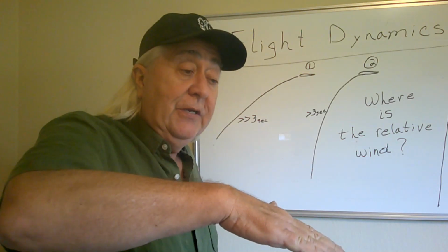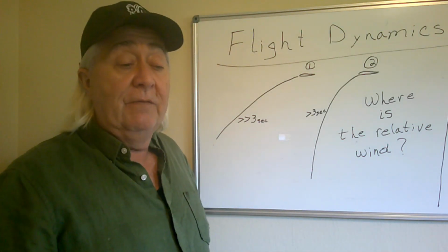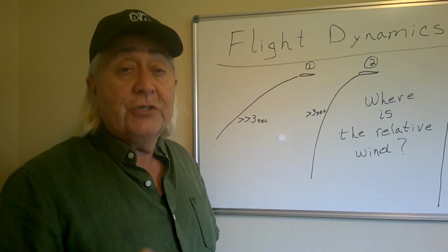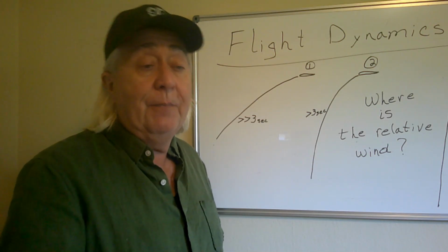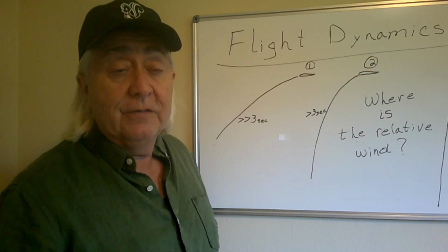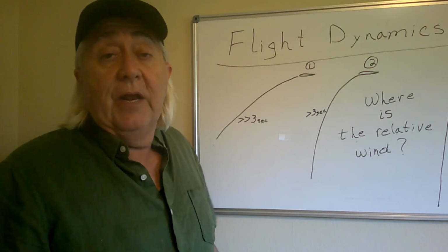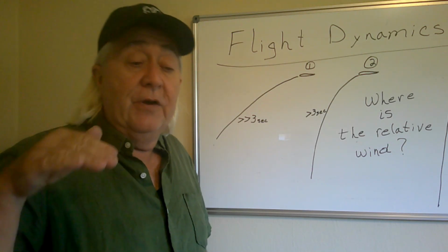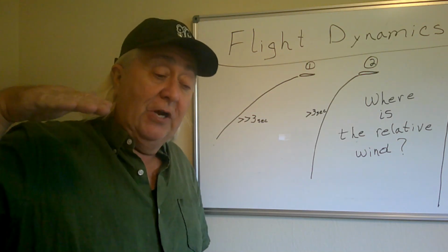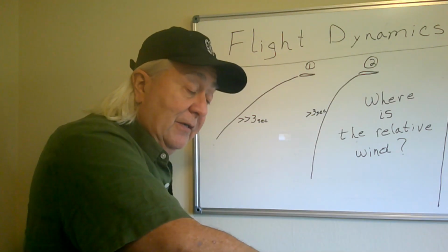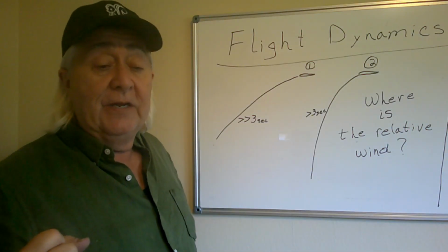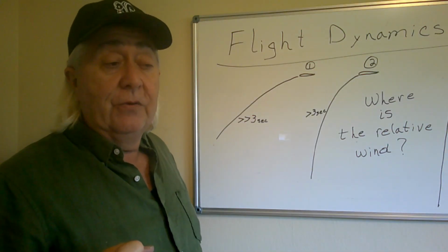And eventually, well, oh, that's too fast. I pull in up elevator, but I need more flap to slow up the land. So you put in more flap, and now you pull in more up elevator, right? Until you run out of elevator. And then you're at some flap setting that's causing this rapid descent rate, and you got full up elevator in, and you can't get the glider slowed up.